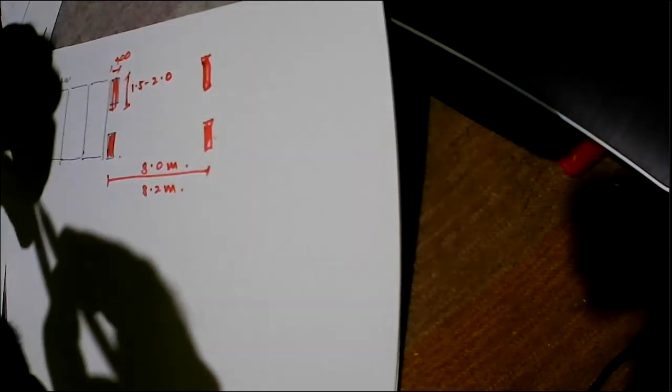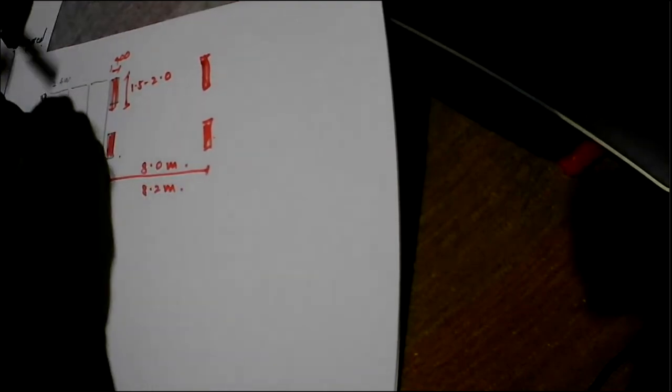So you can see you can create very large columns by having a grid spacing like this, where between two grid lines you can park 3 cars. So automatically you will settle for some grid arrangement like this. The other possible arrangement is, instead of having 3, you will go for 2 car parking spaces, but it's less likely because then you will end up with a lot of columns. So this is another arrangement.